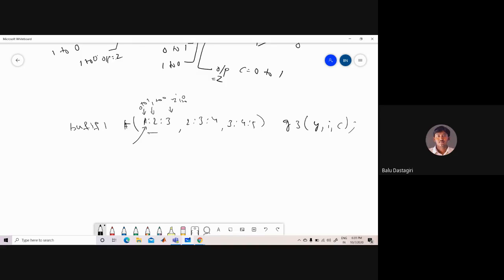The typical delay, that is the average delay associated when you change the inputs regularly, means the output Y going from 0 to 1 takes 2 time units, and 3 is the maximum delay associated when the output changes from 0 to 1. So the first denotes the minimum delay, the second is the average or typical delay, and the third is the maximum delay.